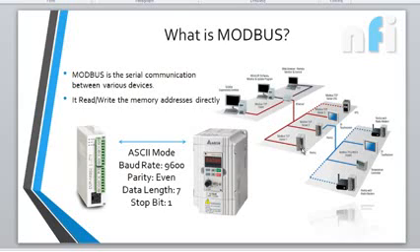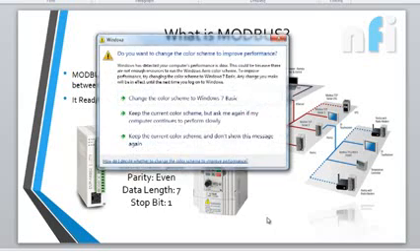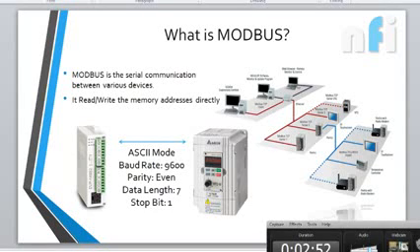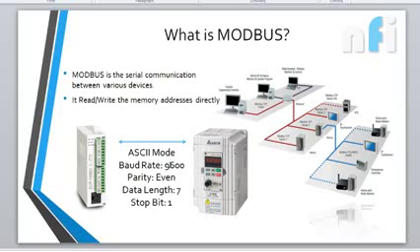If you are directly accessing the memory registers which are inside the drive, that is Modbus. Now we are not communicating via some voltage or current, as we do in a VFD, where we convert 0 to 10 volts into 0 to 50 Hertz frequency. We use a potentiometer to change the frequency. Now suppose you do not want a potentiometer, and you want that to be done by directly accessing the memories. That is Modbus.